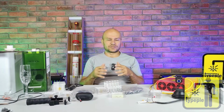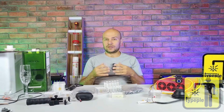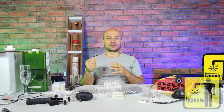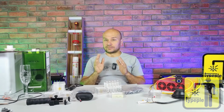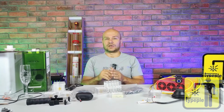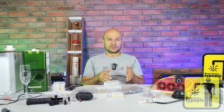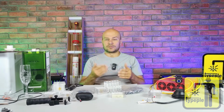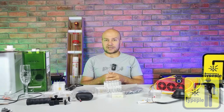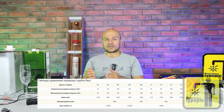The life of such sources, specifically CO2 radiation for example, a metal ceramic tube comes with air cooling and high pressure. So accordingly, the resource of this gas is much greater and it lasts for a longer time. It can be, specifically metal ceramic, on average from 20,000 hours to 100,000 hours. Again, this is the time until total failure, depending on operation, temperature conditions, power usage, and much more. In this case, glass tubes specifically use a low pressure of this gas mixture. Accordingly, the lifespan can range on average from 1,000 hours to 15,000 hours.